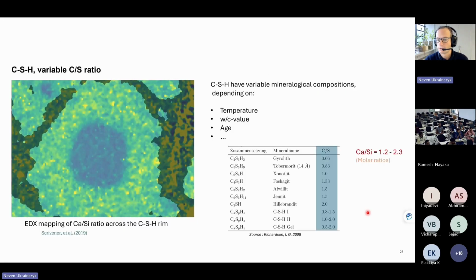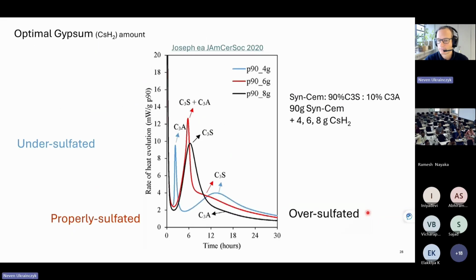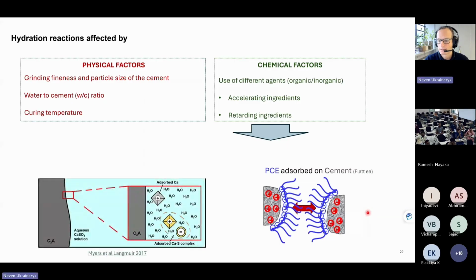So this is the only thing I wanted to tell you. This we already went through. Plasticizers, yeah, that's already explained. Maybe just, yeah, this is the adsorption of the gypsum, of the calcium sulfate on the C3A surface. So this is the sulfate here. The minus is the sulfate, and this adsorption actually blocks the C3A reaction, and this is why we have the setting regulation time. But the moment the sulfate is depleted, this would desorb, and that's why we have strong continuation